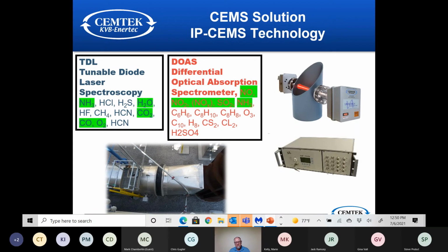CO, CO2, O2, and NH3 within minutes. And we've been running there since August last year, matching up against the CEMS. We've essentially done about 3 RATAs now, passed all of them. We're measuring NH3 slip with the tunable diode laser and the DOAS, and we're getting accurate NH3 on both of them. Both of them passed the RATA test.